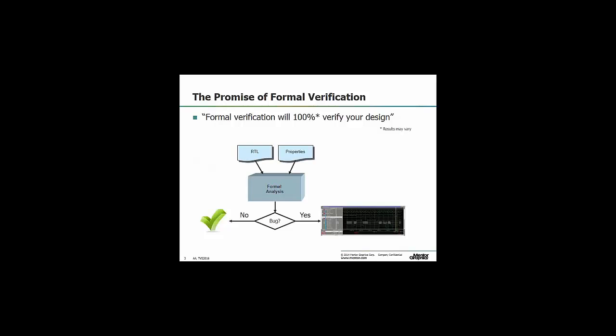So the formal analysis can actually be split in two parts. The first part is you make some kind of synthesis from the inputs, from the RTL and properties, and later you focus on what you have synthesized, and you apply your model checking. I will not cover the synthesis part here. I will focus more on the model checking. As I said before, from the RTL and the property, you generate a big FSM that combines both design and property logic.